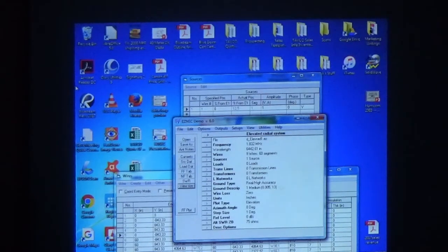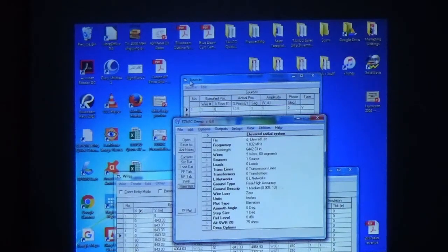If you've got an inverted V, and say it's at 40 feet, and you got 20 feet at each end, and you got a tree next to it, and it's over a house, and there's a tree on the other side, is there a way to tell how that affects the radiation pattern? Not exactly, because you cannot model trees. People in the Antenna Compendium and such have modeled cars, but it's wireframe modeling. They just sort of wire the outline. You just have to give a reasonable representation. You can't do that for a house or a car.